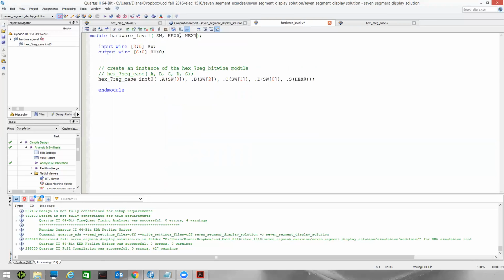So I'm going to add hex 1 here. And it's 7 segments, so I'll just add that to the list here. All right. Now both of these are enabled. If I want to turn this on, I'm just going to copy that, create another instance of this module, give it a unique instance number, and now my output would go in hex 1.